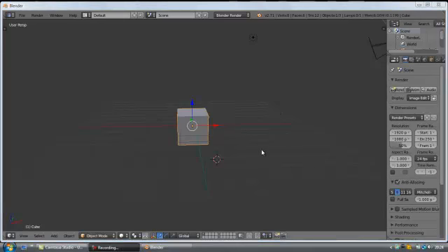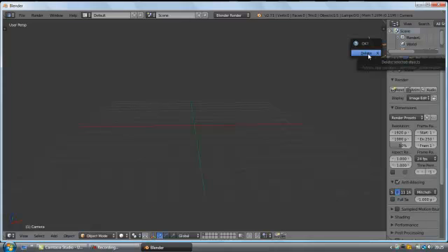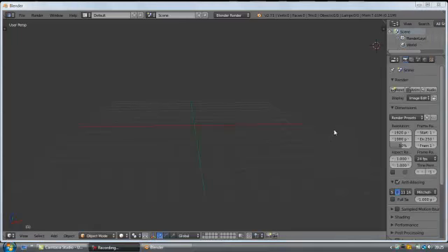And as you can see, when you start Blender, you get 3 objects. You get a cube in the middle here, you get a light source up here, and you get a camera. We don't need any of these, so we're going to delete them. The way you delete stuff in Blender is you right click on it once until it's highlighted. The outline of the object is highlighted in orange, like this cube is here, and then click X on your keyboard and select delete. This is a light source up here. I'm going to right click on it, and as you can see it's been highlighted in orange. Now I'm going to click X on the keyboard, delete. And this is a camera here. I don't need this either, so I'm going to right click on this and then X and delete. Okay, now we're ready to get started.